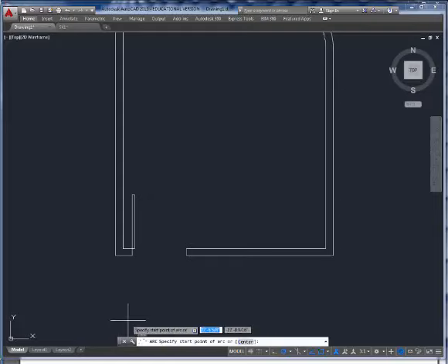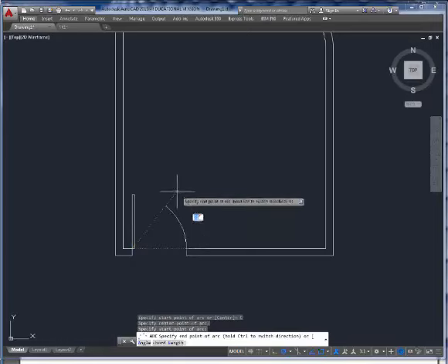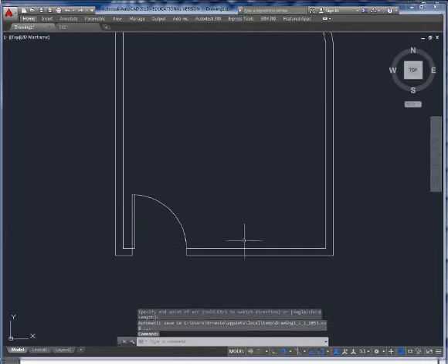We have done the 3-point arc in the past. This time we are going to draw it from the center. And the center is going to really be the hinge position of our door. Right there. Here is our first click. And here is our second click. And the reason is because AutoCAD is positive when it goes counterclockwise. Right, so that's something to remember. We're going to come back and check it a couple of times.